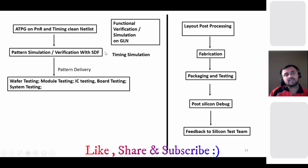and then you generate the pattern and you verify those patterns with SDF, the delay format, in timing simulation, and then you deliver the pattern for the wafer testing or module testing. There is so much testing. Those patterns are the actual patterns which are used for the silicon testing.